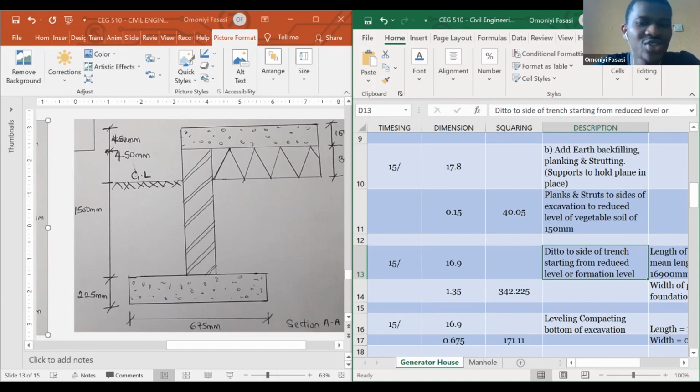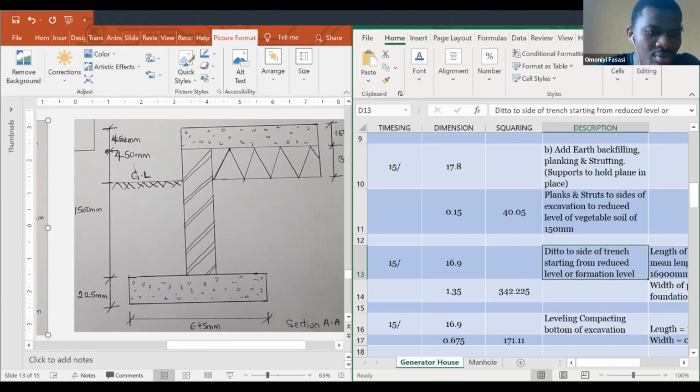The depth of your trench is going to be 1.5, which is the length from here to the soil above the footing, minus 150. The 150 is what we already accommodated for up here. So if you add the two together, you get your normal 1.5. Are you guys getting me? Is that 0.15 a constant value?